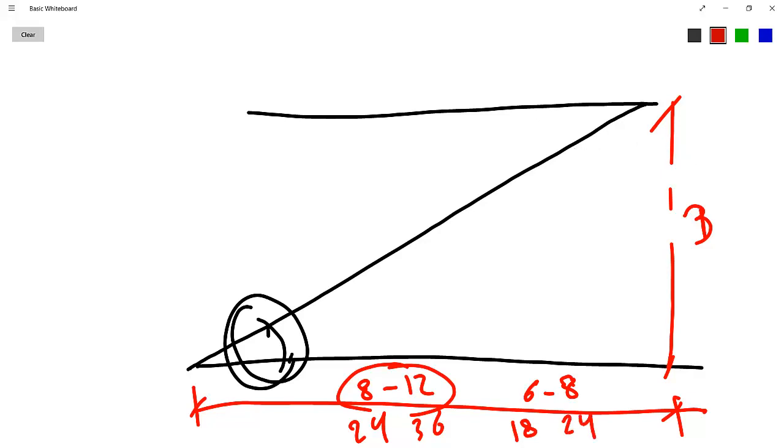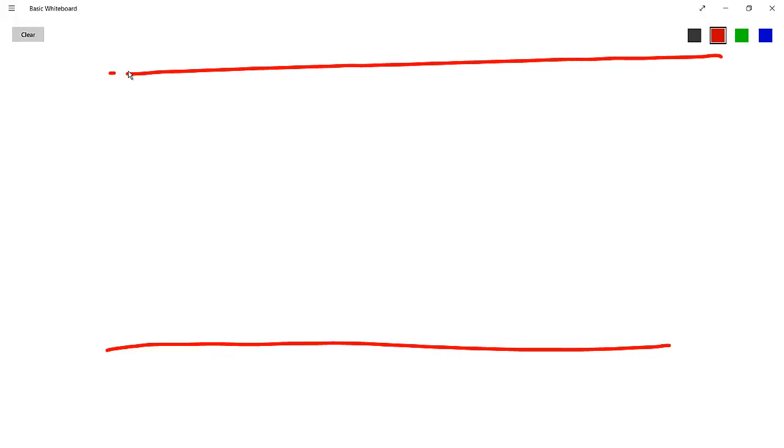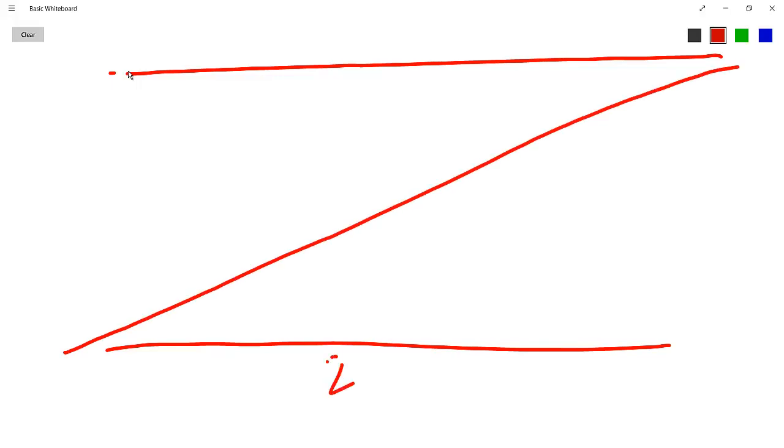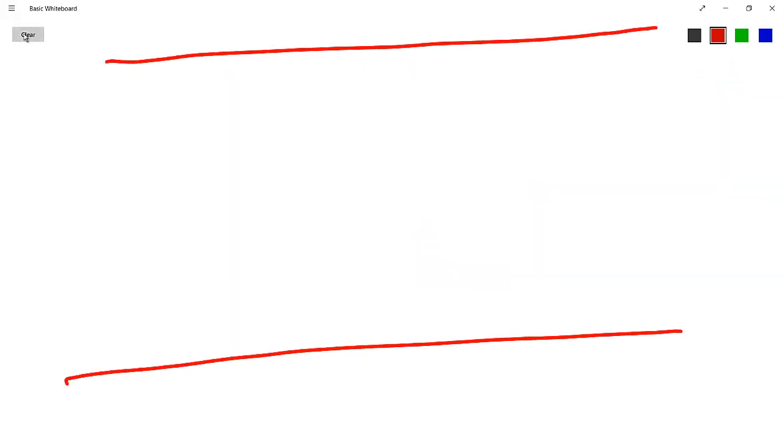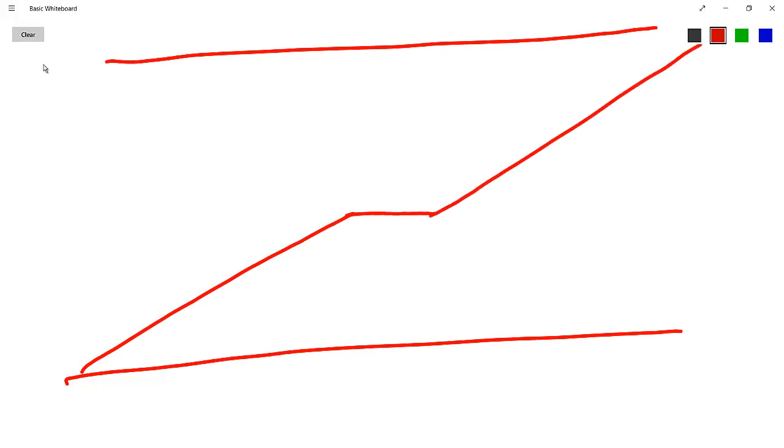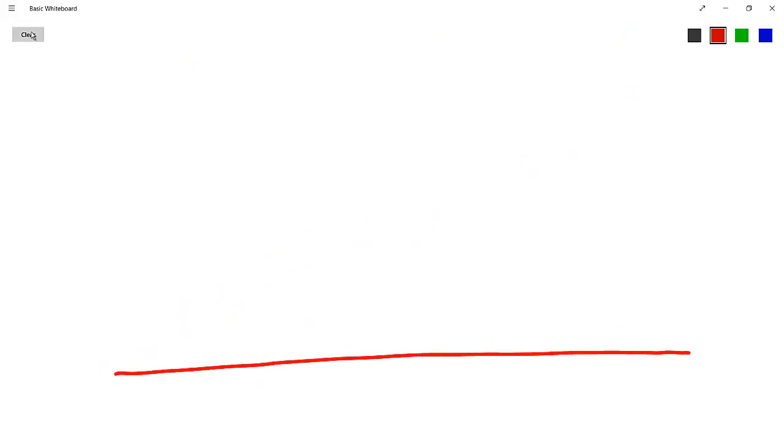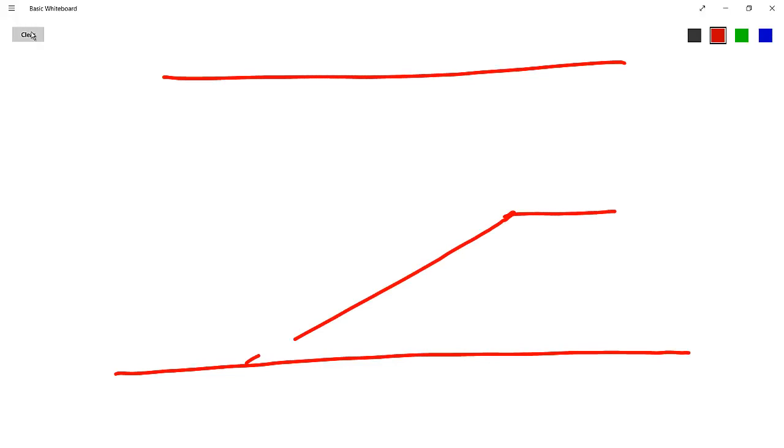So in this case, if we have a floor 3 meter height, we need to design a ramp. Of course, designing a ramp, it could be just one flight of 24 meters, and this is 3, or it could be, this is the first level, second level, one flight and then landing and then another flight, the same as stairs.